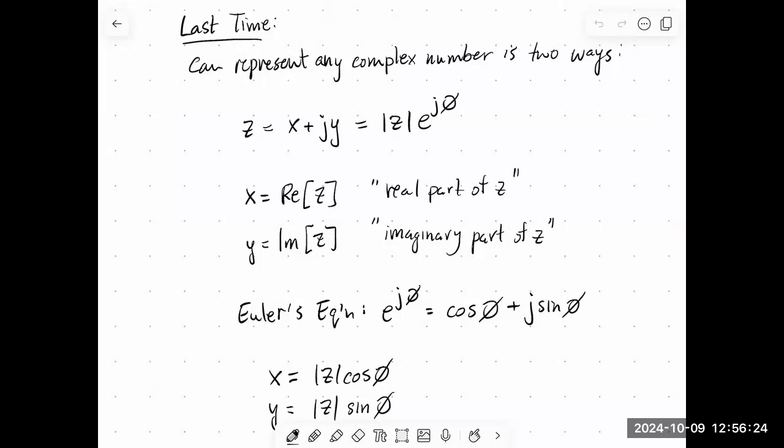It's too late to ask one more question. Maybe. What is it? I'm sort of stuck right at the end of the third question. So I think what you want to make use of is: if you have two components in parallel, it doesn't matter what they are, the voltage across them always has to be the same. And if you have two components in series, whatever they are, they have to have the same current. So those are the tools or the information that we need for that particular problem.